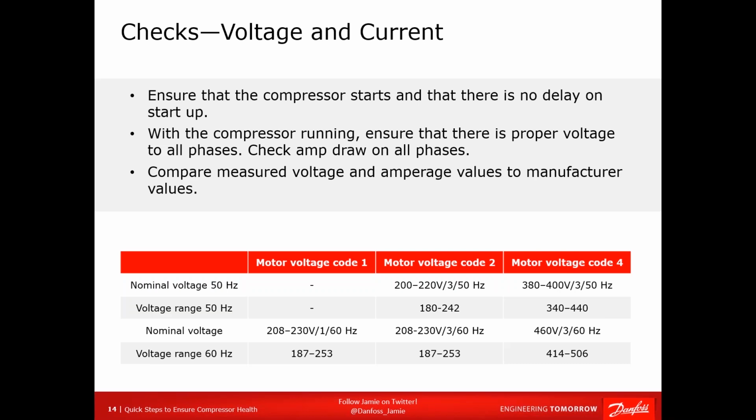While it's a great idea to check voltage before you start the compressor, think of a car battery. If you've lost some cells in your car battery, you can measure the voltage with no load. It'll say 12 volts. But as soon as you try to draw power from it, the voltage goes into the toilet. So make sure that when you check voltage, you do it again after startup so that you know the power supply can handle the load you're putting on it.